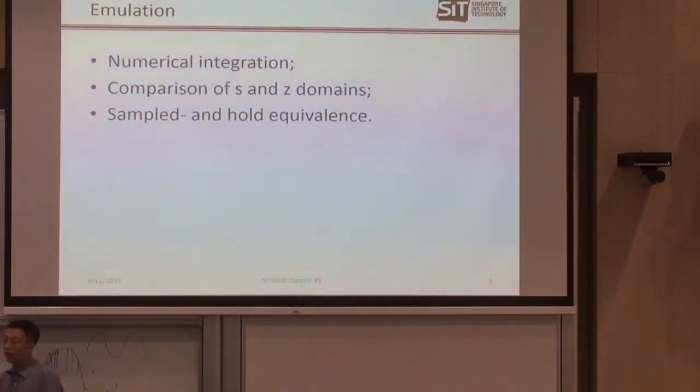On the other hand, we also want to have some mathematical tools for you to design, for you to do analysis, for you to come up with certain good controllers. So what we have is the Z function. If you talk about the mapping, differential equations correspond to difference equations, and your S function corresponds to the Z function in the digital domain.